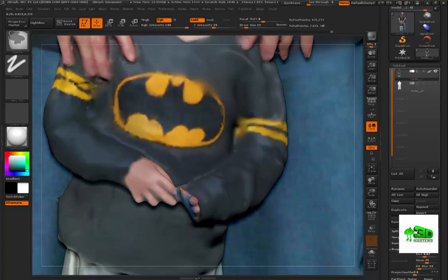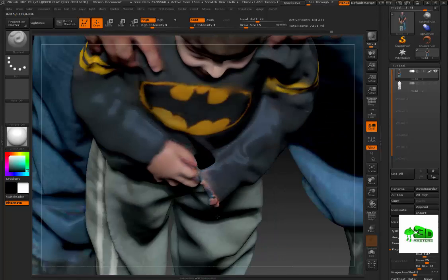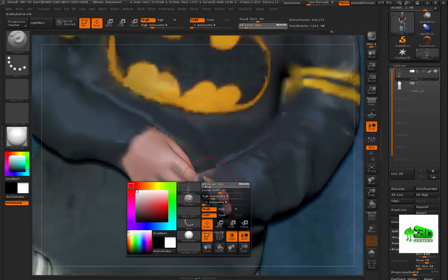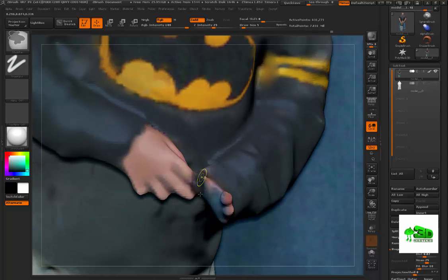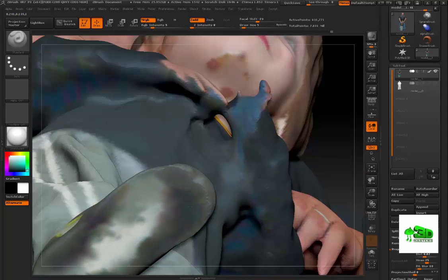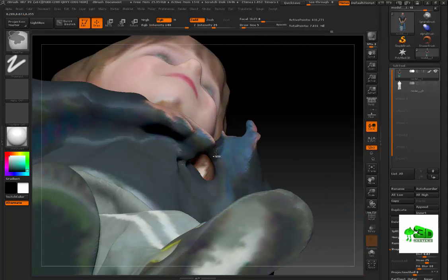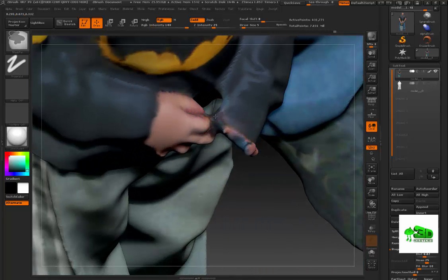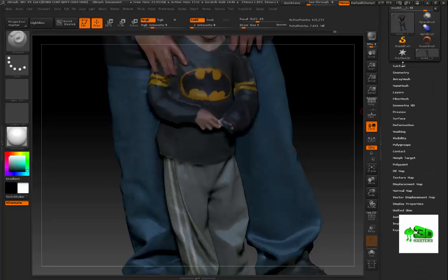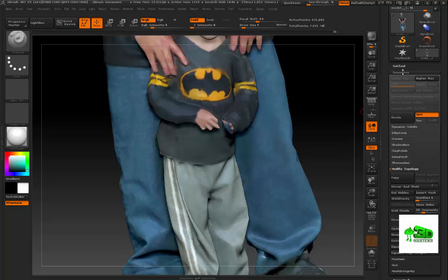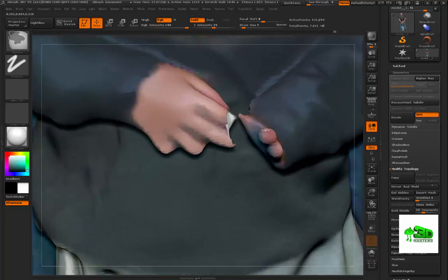Alright. Now the last part of this was to fix the hand. We need to make these two pieces not connect. So I'm going to go ahead and mask these by holding down Control and just painting in between there like that. Let's paint right there so that we can actually disconnect those two pieces. Okay. Hit Control and just left mouse click. To reverse it, go to Hidden. Visibility, Hidden, and then go back to Geometry, and then go to Delete Hidden, and then Connect Holes. Alright, and then we got it separated there.